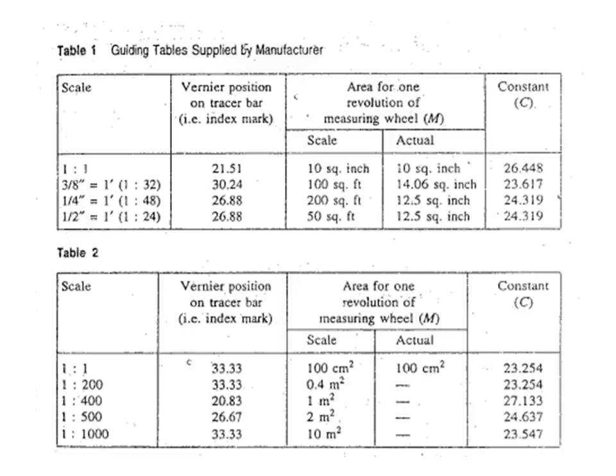Then the computation of area from field notes is done in two ways. In step 1, in the cross-staff survey, the area of field can be directly calculated from field notes. During survey work, the whole area is divided into some geometrical figures such as triangles, rectangles, squares, and trapeziums, and then the area is calculated by adding all the areas.